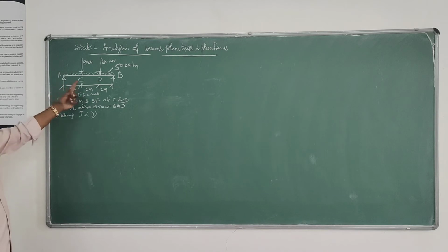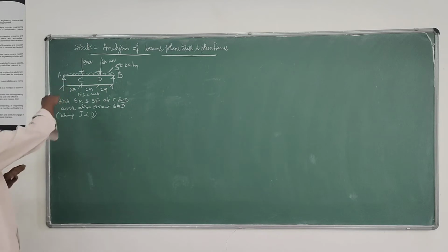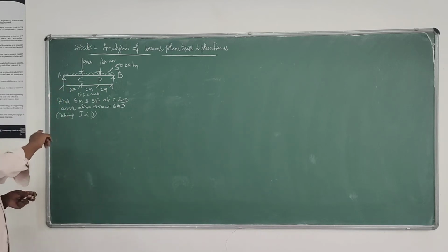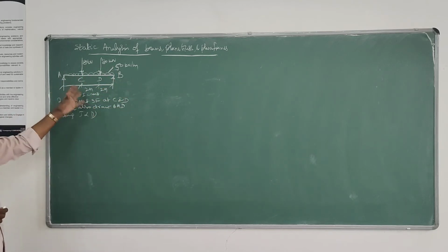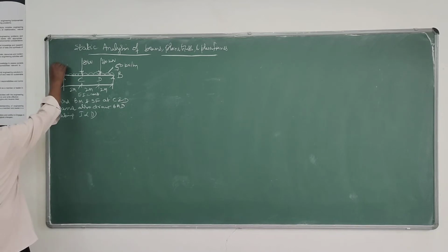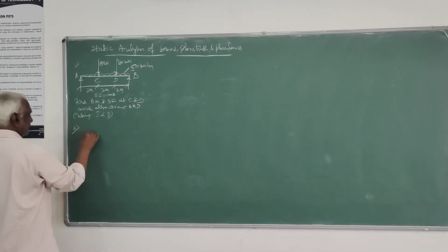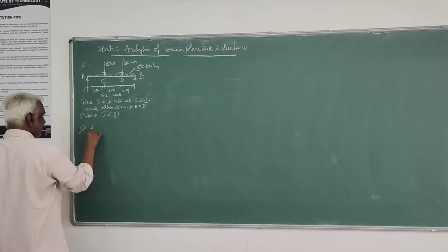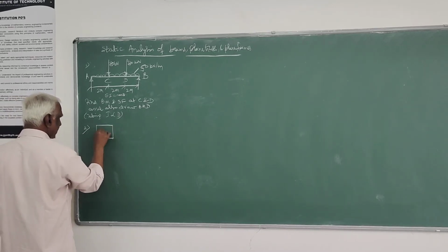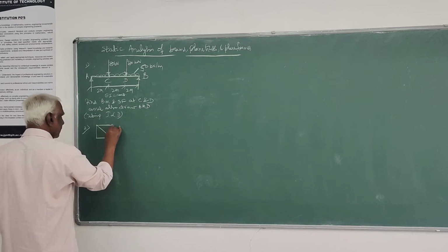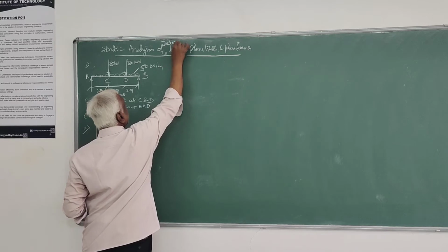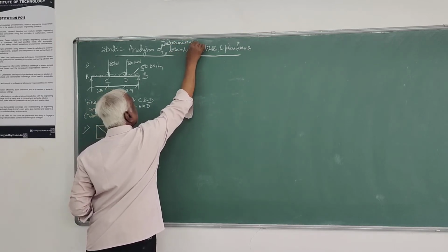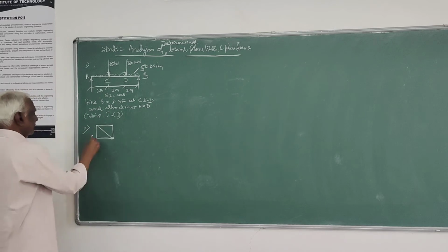You can first find MC and MD; MA and MD are 0. Because you know the variation is always a straight line, you join the points and you will get the bending moment diagram. Similarly, shear force also. This is on beams. Then, by method of joints, you can solve these problems on trusses. Only determinate analysis of determinate beams, plane truss and plane frames.